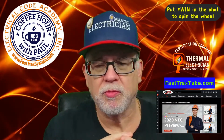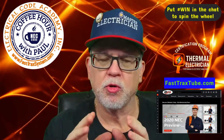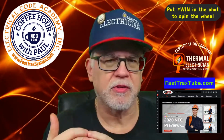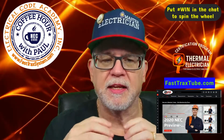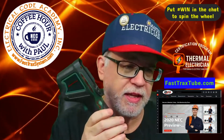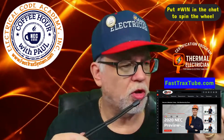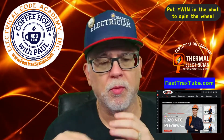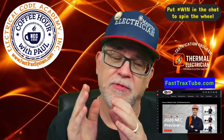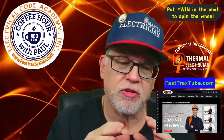But we also created a program geared towards things like data centers, which have to be up and running. And that's a whole separate market for a thermal electrician who's trained in it to understand the nuances when it comes to data center operation. And the electricians that work in these data centers need to understand that you can head off possible problems down the road by understanding the concepts of thermal imaging, and understanding that it's not just taking a thermal camera like this or any other ones that are available and simply taking a shot of something and being able to interpret that image so that you don't do what's called the cry wolf syndrome. And what's the difference between a poor connection, a weak connection versus an improperly sized conductor or an overloaded breaker? What's the manufacturer tolerances of their breakers? We try to give you all this stuff so that you have it. That's what a thermal electrician program is going to be doing.